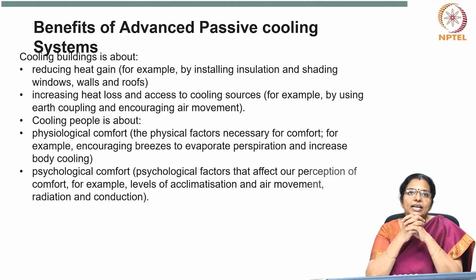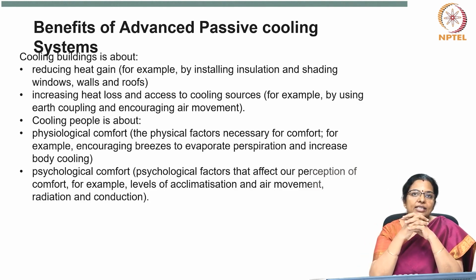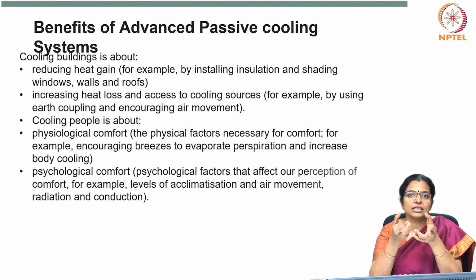Cooling a building is about reducing the heat gain, for example, by installing insulation and shading windows, walls and roofs, and increasing heat loss and access to cooling sources, for example, by using earth coupling or encouraging air movement.